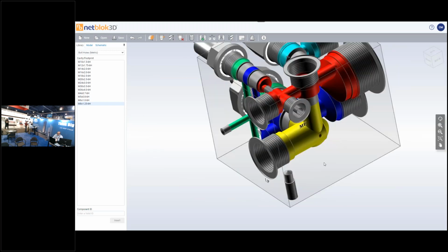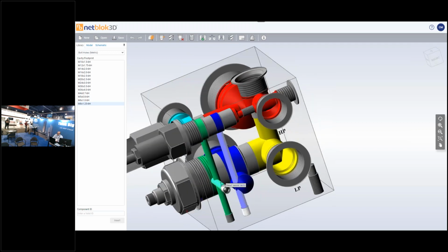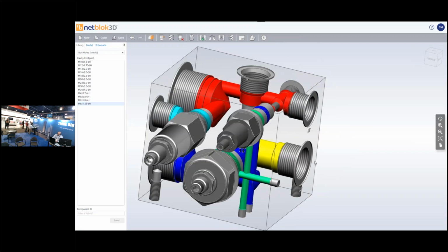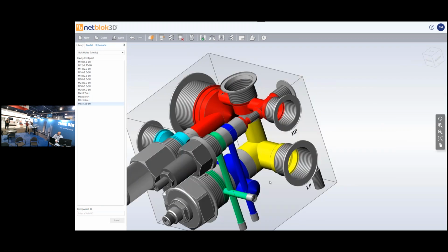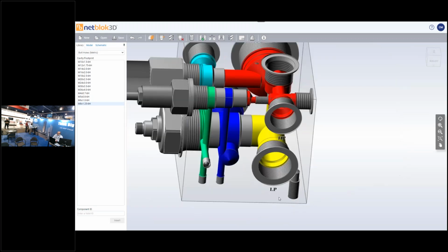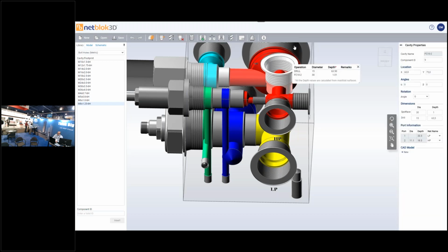So like I showed, display wall thickness is very handy because it helps you with measuring on the fly and isolating distance between cavities. So this block looks good, but there may be situations where you have more critical situations. Another command to verify what you are doing is the display machining sequence. So if you need to check which cavity is used.